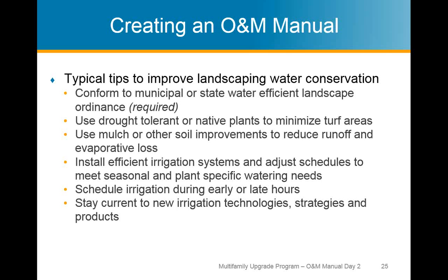The obvious one being, we don't want to schedule our irrigation for high noon. All the water is going to evaporate before it gets a chance to get absorbed by the soil, and you've just wasted a bunch of water and the plants are going to die anyway. So we'd like to do it in the late hours or the early morning hours. Just personally, I think early morning is better because it doesn't keep your grass wet all night. But either one of those is acceptable.